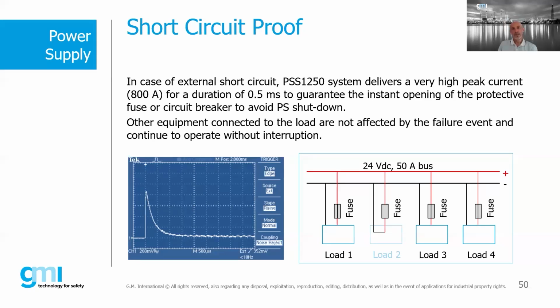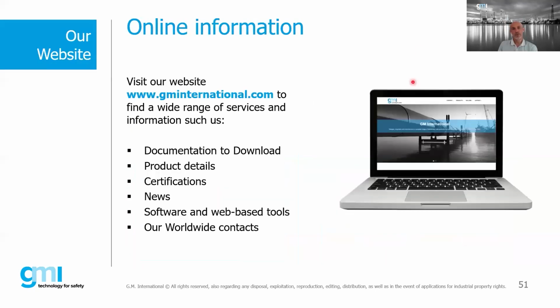Okay, thank you, Gabriele. Of course, this is information maybe you never heard about power supplies. This is probably a first. The power supply is very significant in the system and must be considered in the SIL calculation, because a power supply is not always a fail-safe device, not really fail-safe. It can be fail-safe, but there are situations where, especially with switching power supplies, it can be really dangerous for the systems. All these things can also apply to the chemical industry. There is a question about it. Yes, of course, chemical requires SIL certification, SIL instrumentation.